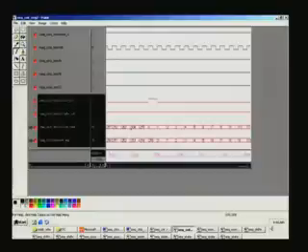So, I think it would be better to have start and end points, that should make it very clear to you. And you can see here the counter edge is 250, 251 and so on, corresponding to 250 it is a pre-increment. So it is 251, and right at this point of time you notice after 255 the counter next has become 0, and this counter 255 is appearing only at the next clock edge here.